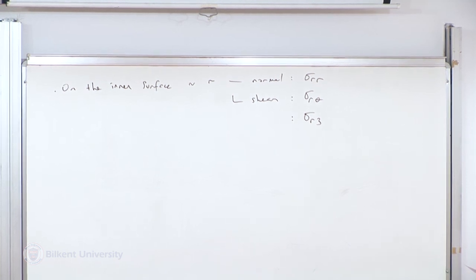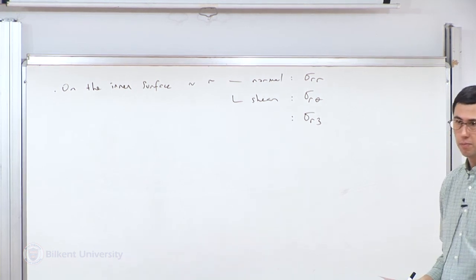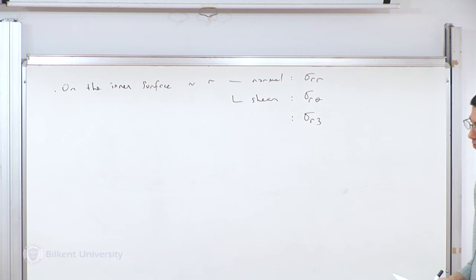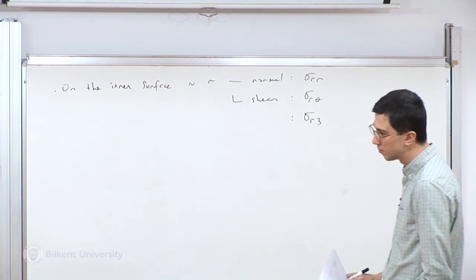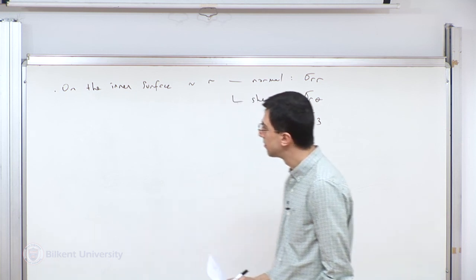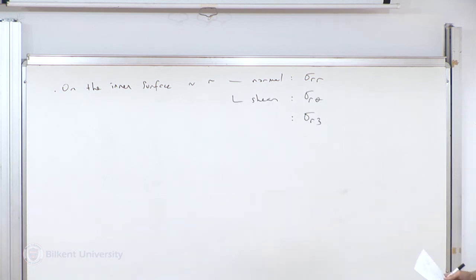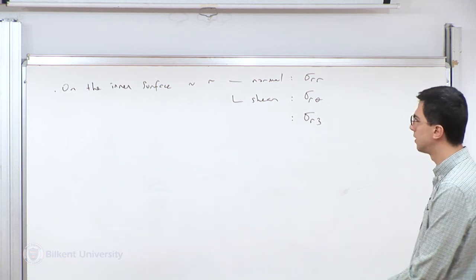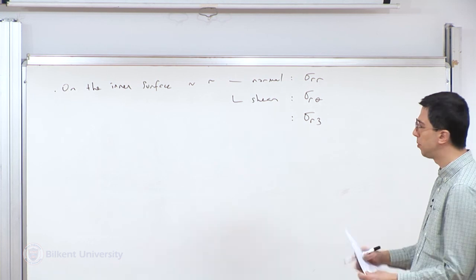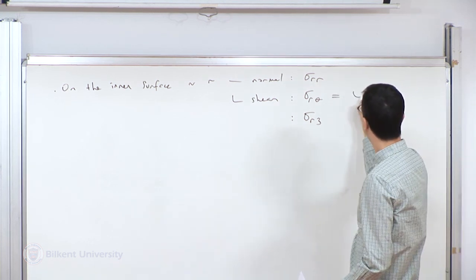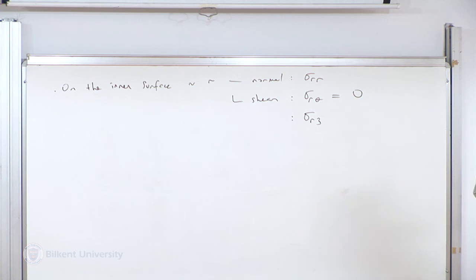Anything zero? Displacements perhaps are a little bit easier, right? But now we're talking about stresses. Sigma_r-theta, because I am not applying any torque. It's zero. How about sigma_rz?